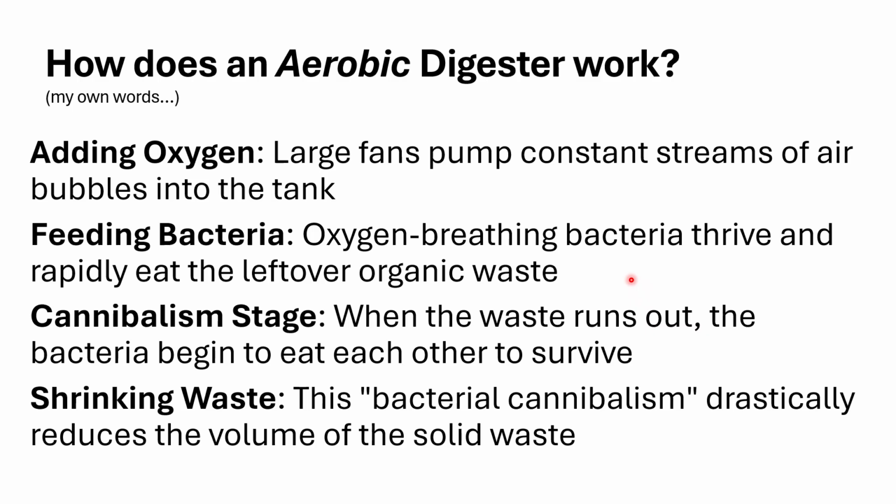Let's eat, okay? Now, here's the thing, though. If that food, that incoming waste stream, that incoming sludge that we're wasting from the primary and secondary clarifiers, runs out, or it starts to get very low in organic or BOD content, those bacteria are going to look around and they're going to say, we're still hungry.